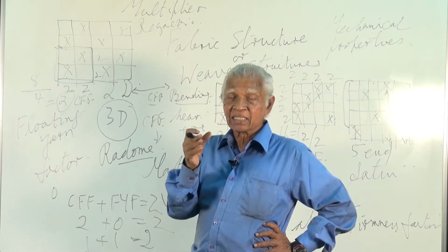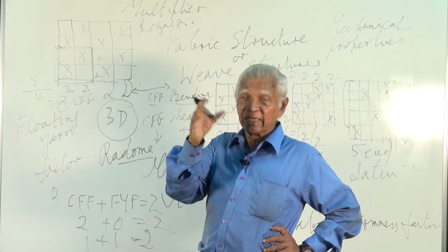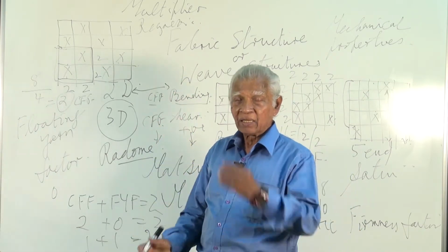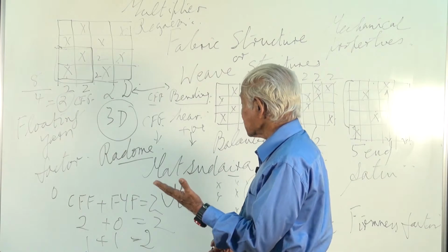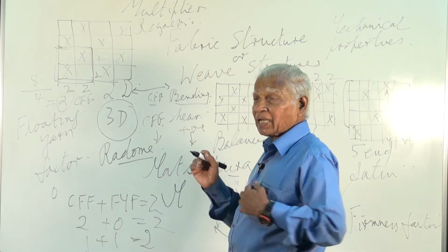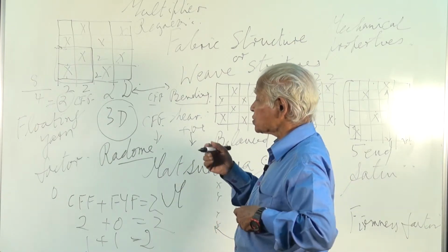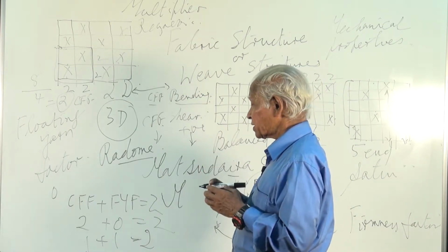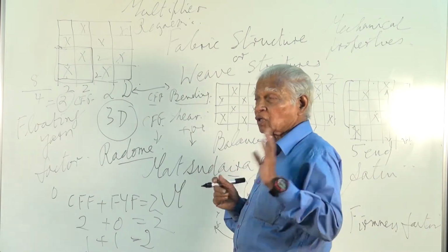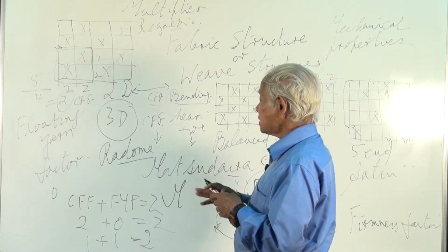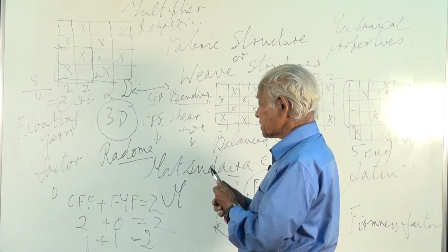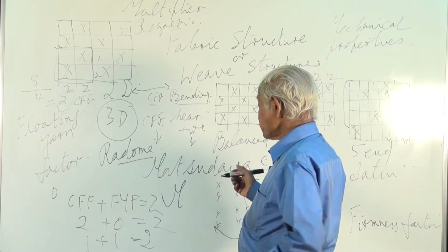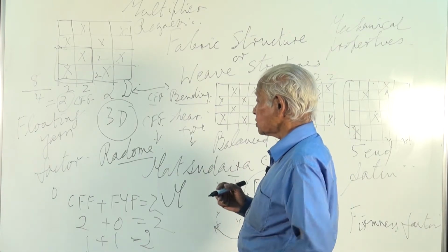And when we conducted studies on fabrics which differed only in structure, but were identical in all other respects like fabric weight, thickness, etc., it was found that the fabrics which had a larger number of floats had very good resistance towards ultraviolet radiation, that is, a good ultraviolet protection factor. In fact, plain weave, although it has good strength, is not suitable for certain other applications like ultraviolet protection factor and air permeability.